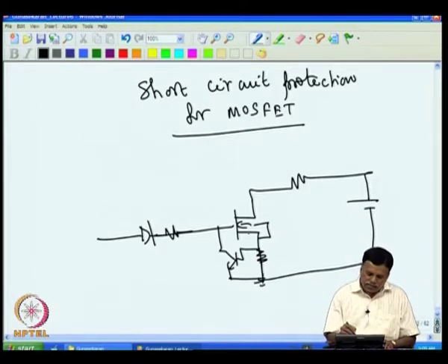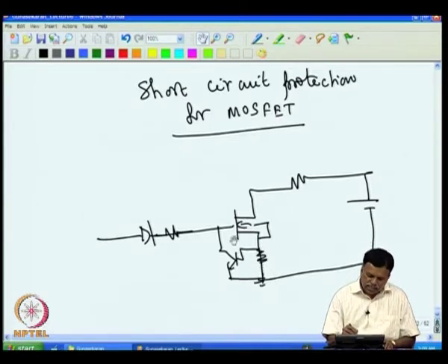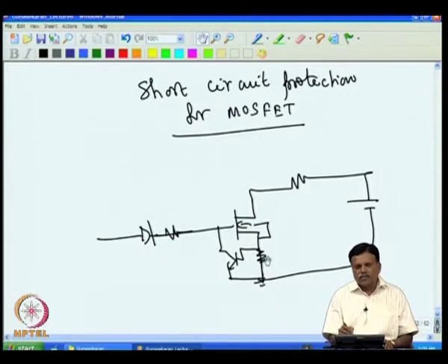So, in a normal case when the heater is on, the voltage across this will not be 0.6, it will be 0.2 or 0.3. So, this transistor is not activated and it is not playing any part, and the heater works normally. Whenever this is on, the heater is on, and whenever this is minus or 0 volt, the heater is off.